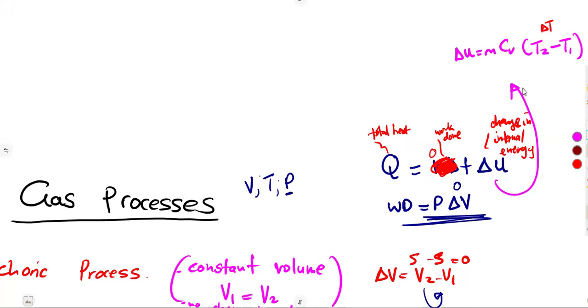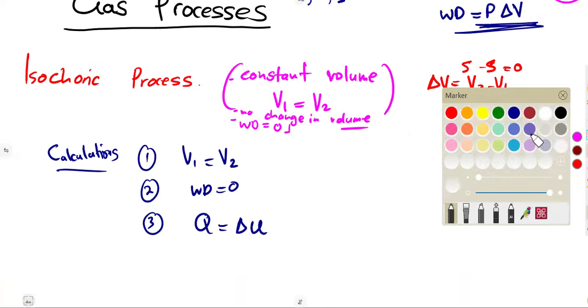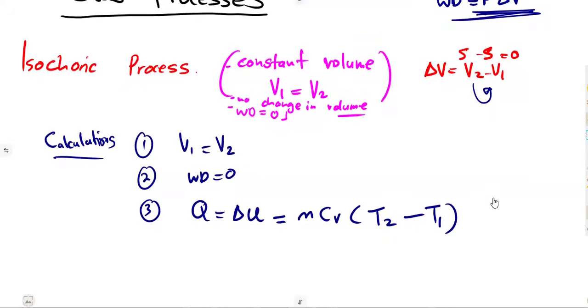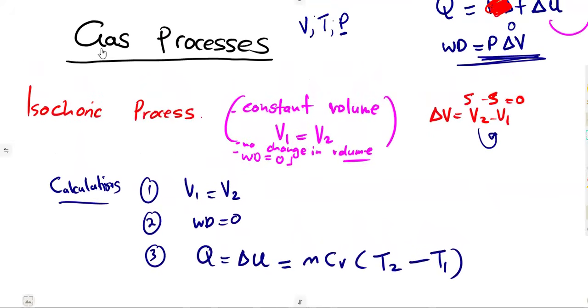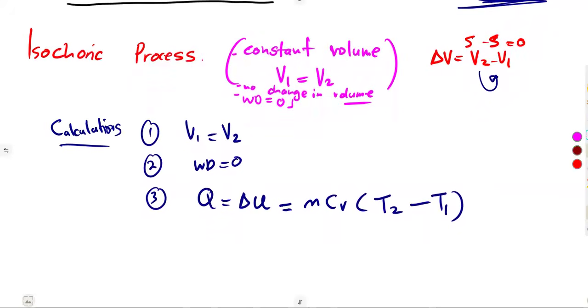That is the change in temperature. So if we are saying Q is equal to the change in internal energy, therefore in place of Q, we are going to write the formula that is Q is equal to the mass, specific heat capacity times what? The change in temperature, T2 minus what? T1. So this will be the consideration. And do not forget, guys, as long as you are dealing with a gas, always the PV is going to work. So the PV formula can be used.